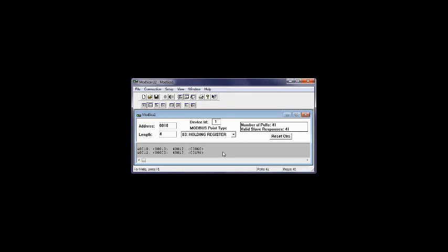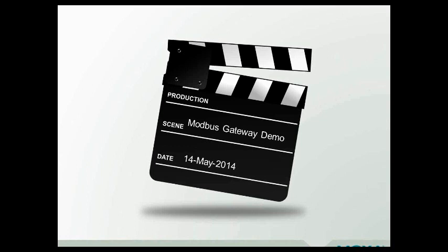Of course, I simplified this and didn't show you the wiring that needs to take place and knowing the specific parameters of your device. But with that and having your gateway, setting up your network settings, setting up your operating mode, specifying your serial port settings, and then pointing your software to that specific device, I think you can quickly see you can get that serial device within 15 minutes up and going on your Ethernet network and collecting data remotely from, whether it be your programming software or your SCADA system, HMI. Very easy to do this, and a pretty powerful tool with that.